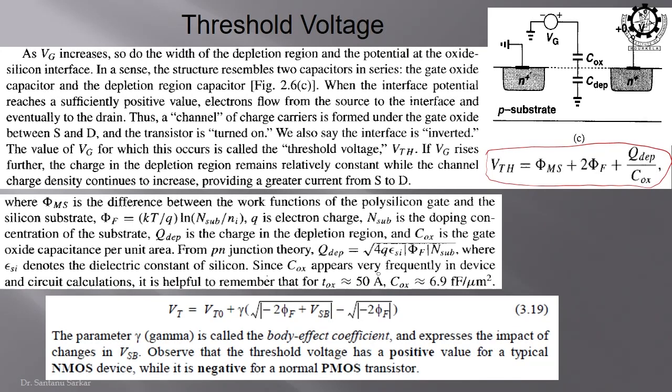Now, what happens if you increase this voltage further, if your gate voltage is above this VTH? When your VGS is equal to just VTH, you are up to the space charge region, but if your VGS is above VTH, that we call the overdrive voltage. Up to VTH you can think of it as 0, then it is the delta, that is the excess voltage.